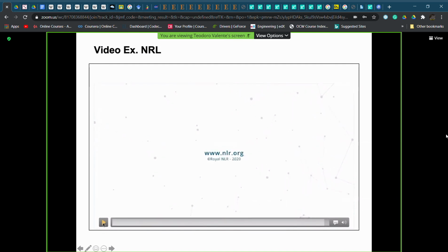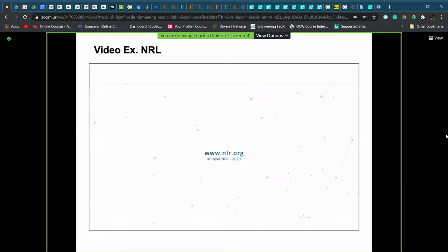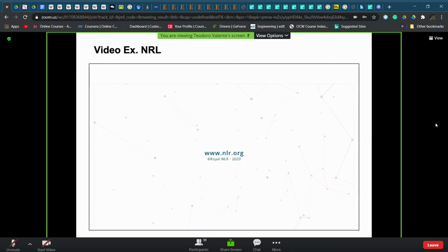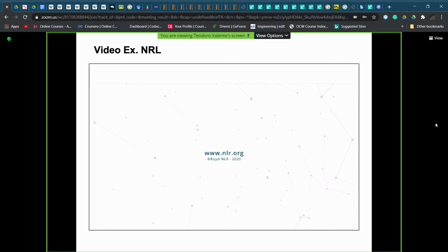Okay, that one was just one example. I don't want to make any advertisement again, but you have seen, let me say, with your eyes how by starting from a bed of powders we can, by melting and adding layer by layer, reach the fabrication of a final component, which is the general concept of additive manufacturing. With this, we have concluded our discussion about powders, let me say powder metallurgy, so you also have an idea of the most important technologies which can be used for the fabrication of bulk components.